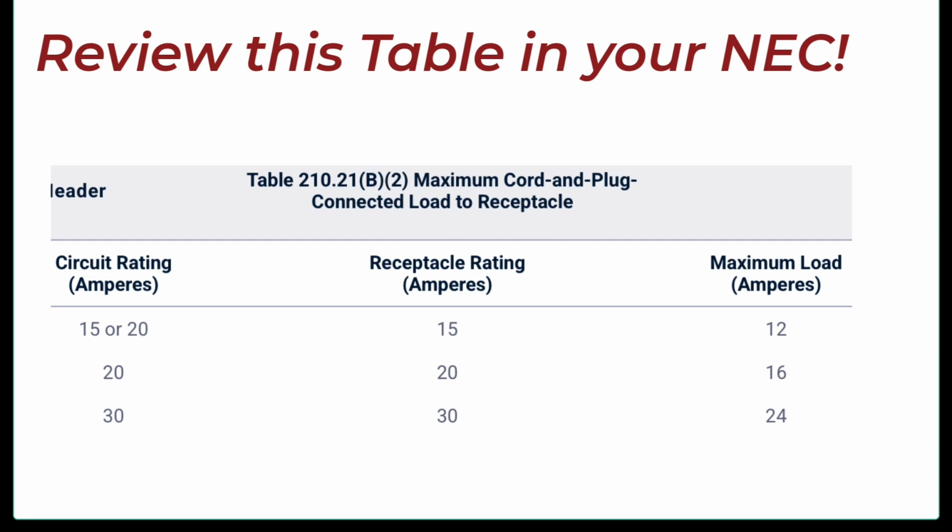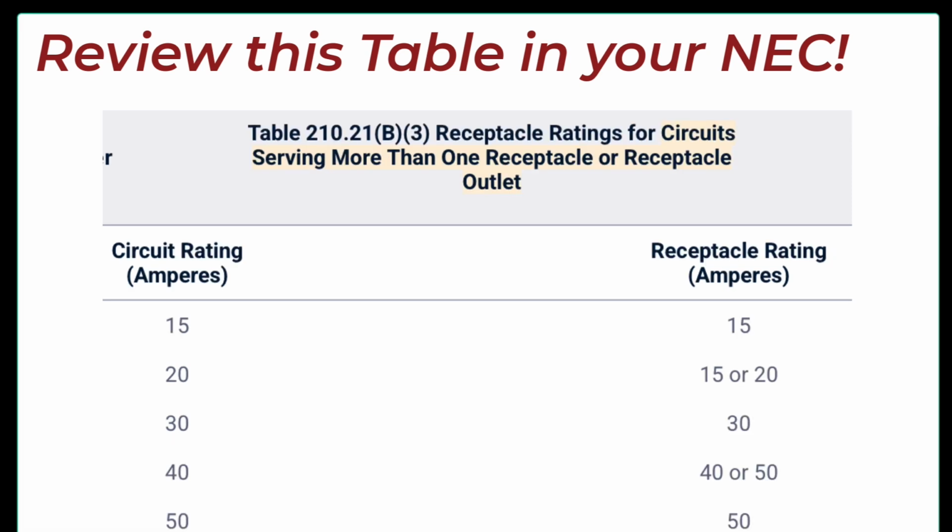It says the receptacle rating in amperes would be 20 amps, and the maximum load then would be 16 amps, by design, for cord and plug connected equipment then.